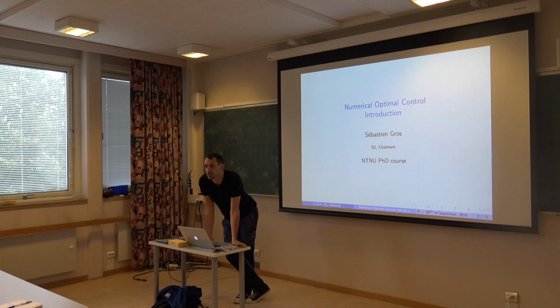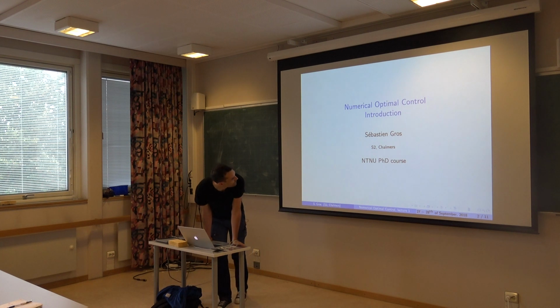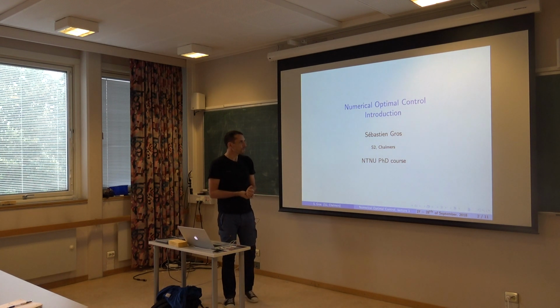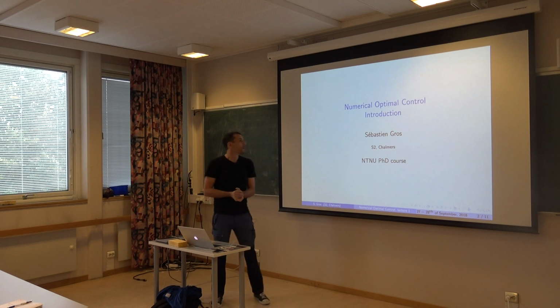So if you have linear dynamics and convex inequality constraints and convex cost functions, then you do have a convex problem, like linear MPC. It's a convex problem you have in the end. But if you solve more complex optimal control problems arising from generic ODEs and so on, you can usually forget convexity. And we have to live with that. And it's not such a big drama, actually.